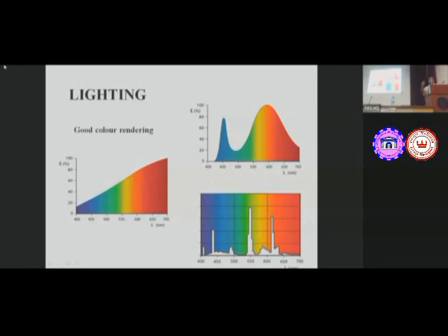Basically, in most cases, the LEDs we use are blue light emitting LEDs. We put a yellow colored phosphor at the top. Just by mixing blue and yellow, we get white light. So we can see there is a sharp maximum. There you can see there is a blue peak over here and a yellow peak over here. Just by mixing that blue and yellow, we get white light. So that is the case for most; 99% of the lighting using LEDs uses blue light emitting LEDs.